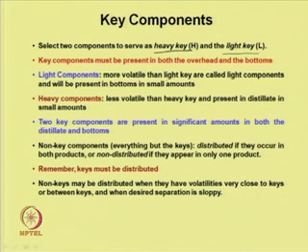Light components, the more volatile components with respect to the light key component, will be present in the bottoms in small amounts. And heavy components, which are less volatile compared to the heavy key component, will be present in the distillate in very small amounts. The two key components, heavy key and light key, are present in significant amounts in both the distillate and bottoms.